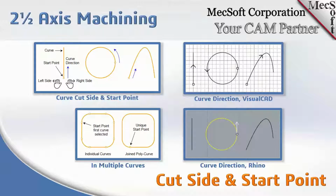And then on the right, we just see the different indicators of the start points and directions of curves. So basically, understand here in profiling, the tool is going to start at the start of the curve. It's going to cut on the side of the curve that you specify: right side or left side for an open curve, inside or outside for a closed curve.